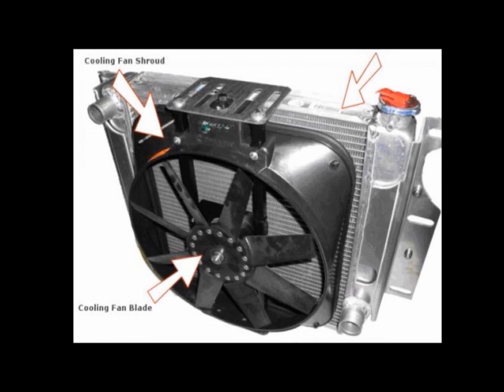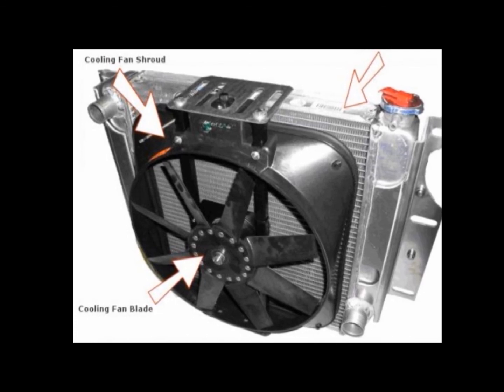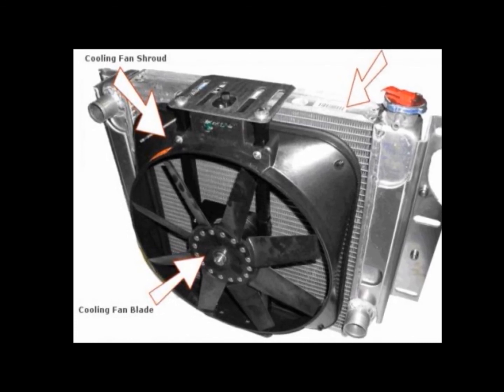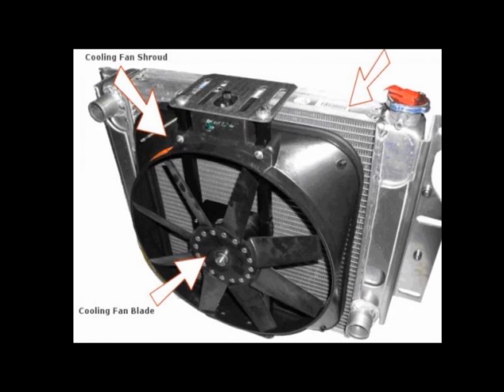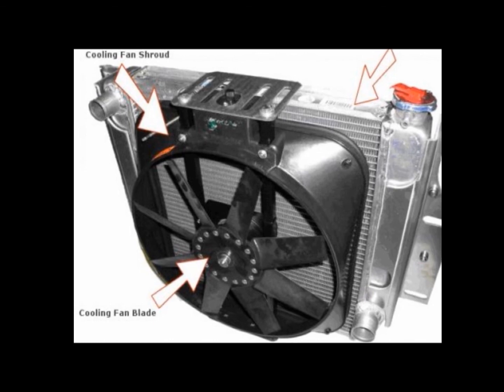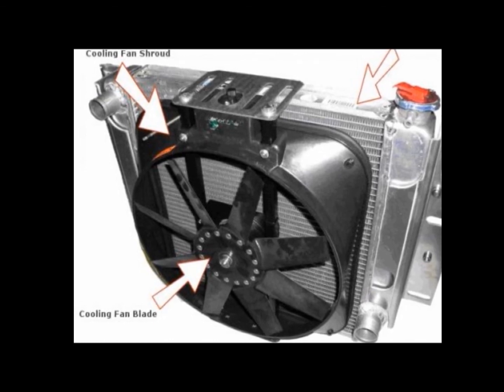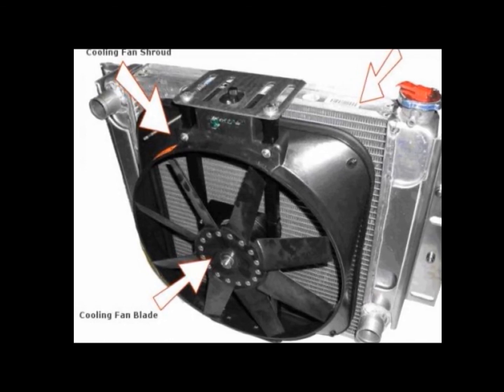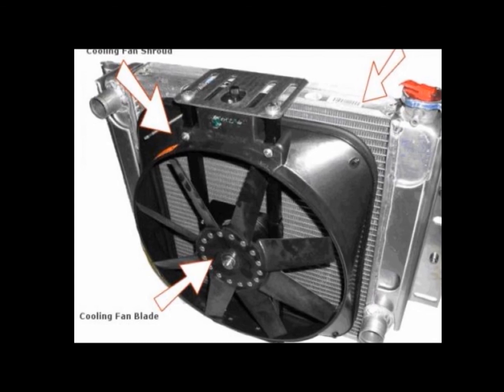As it circulates through the tubes, the coolant transfers its heat to the tubes, which, in turn, transfer the heat to the fins that are lodged between each row of tubes. The fins then release the heat to the ambient air. Fins are used to greatly increase the contact surface of the tubes to the air, thus increasing the exchange efficiency.